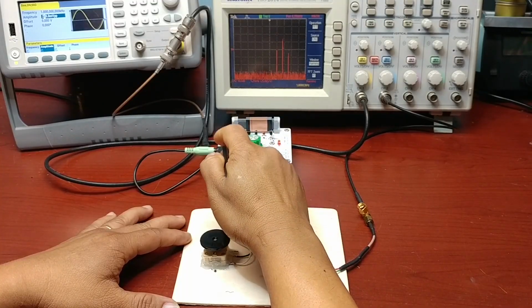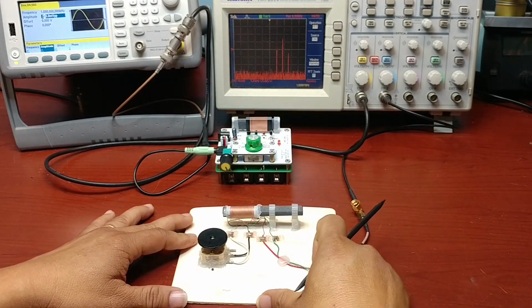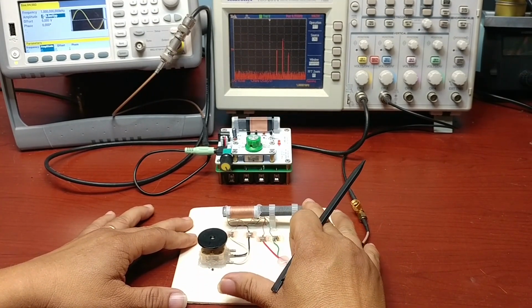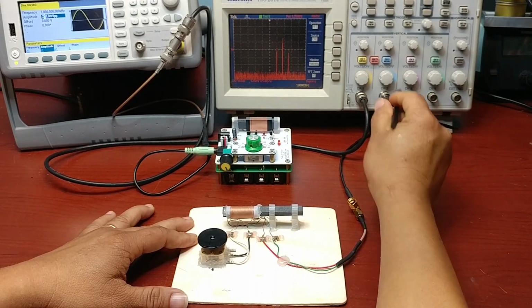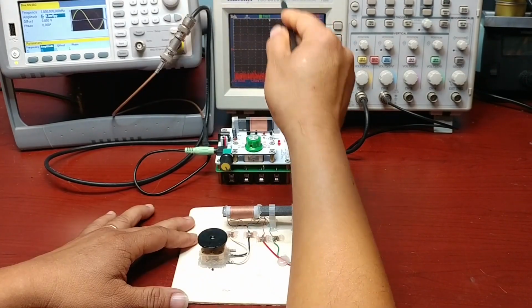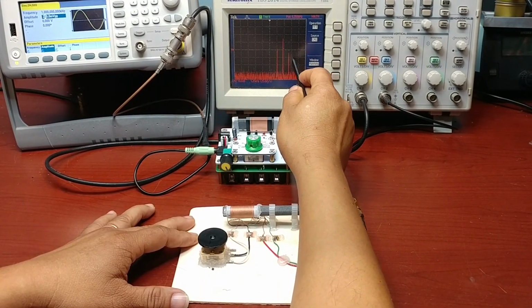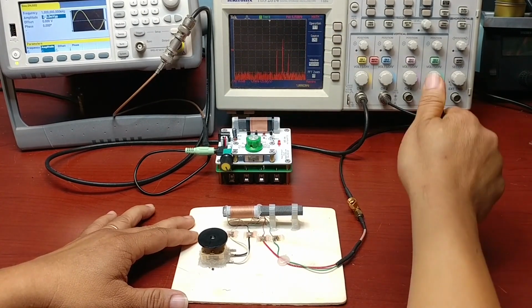At the transmitter, we have a 1 kHz sine wave signal mixed with the 800 kHz carrier signal, producing the AM signal, and transmitted out. The antenna receiver circuit receives the radio signal, and it's shown on the scope. When looking at the signal in the frequency domain, we see three frequencies: 800 kHz, 799 kHz, and 801 kHz.